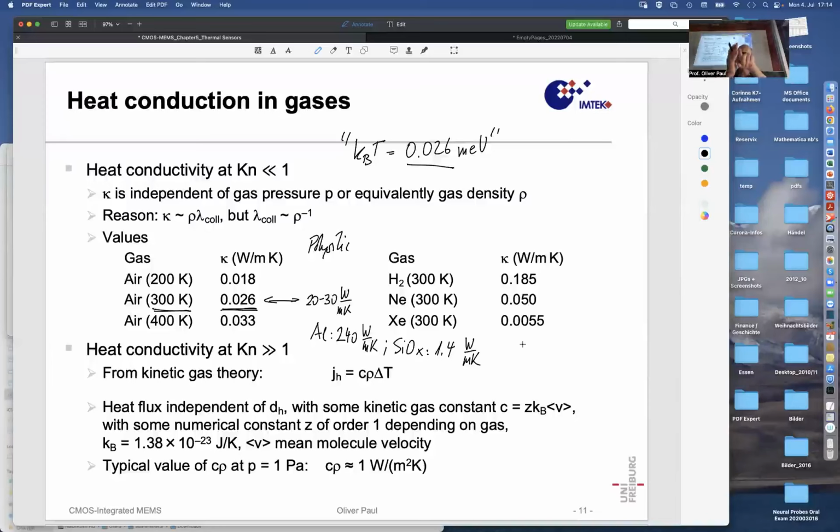And so that means that we can have better insulation through the windows. It's a bit expensive, and xenon is rare, so it's better not to waste it on such applications. The ideal thing would be to evacuate. Then you would have air at zero pressure, and that does not conduct.